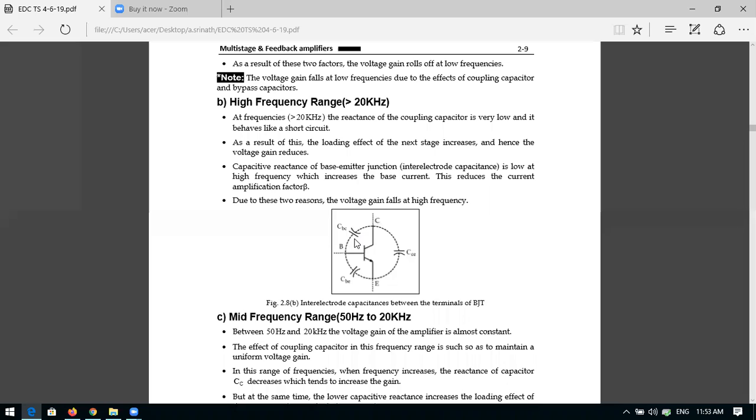The capacitive effect is more. Physically, you cannot connect the capacitors here like this. That is the reason they are drawn in dotted lines; they are not physically appearing. But whenever the signal frequency increases, the capacitive effect comes into picture. A capacitor is nothing but a simple two plates, two electrodes close to each other, with a dielectric. So that is the effect in the higher frequency range.